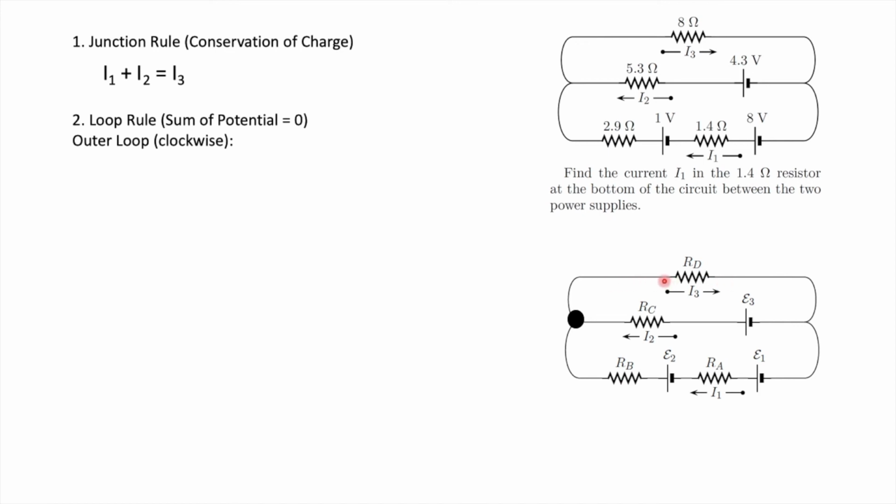And so my test charge here, as I explained earlier, the potential drops as it goes from high potential to low potential. The potential energy of the charge decreases, and potential from Ohm's law is V equals IR, so that's IR. I should have written that I3 times RD, but the location doesn't matter. And that's negative. That means the loss of potential energy.